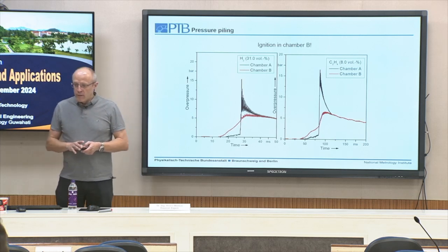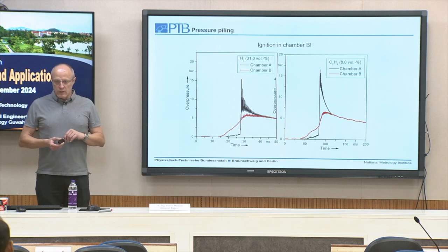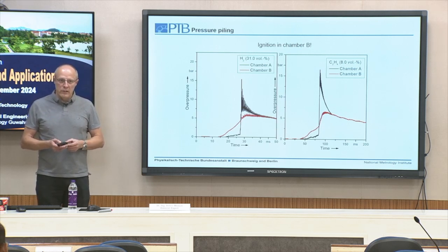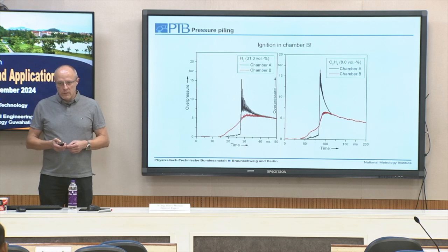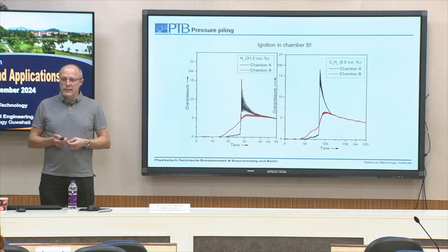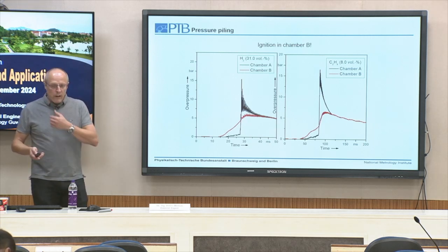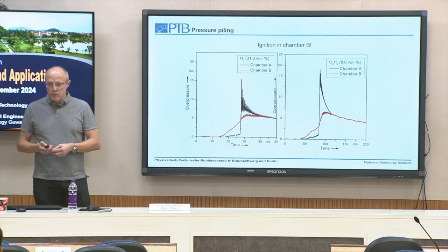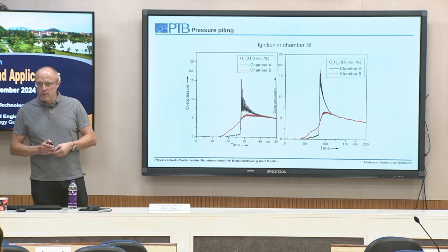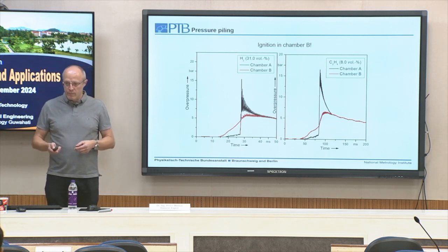So this is a very sensitive procedure, and therefore if you have to measure the explosion pressure in a complex geometry, first of all it's mandatory to do this because you cannot calculate it in advance, second you have to perform some tests, and finally you often get surprising results. No one expects 40-50 bar in a simple geometry, but it can happen.